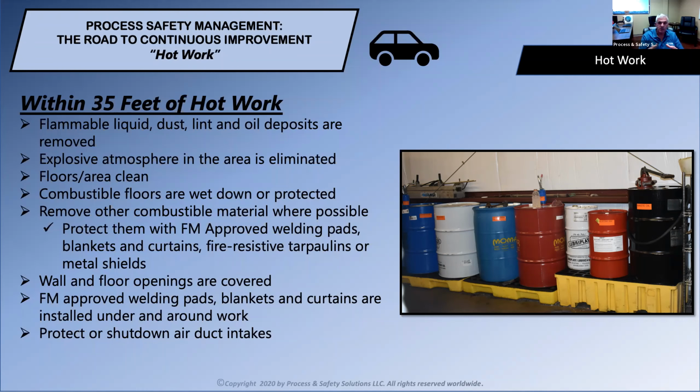A lot of times within facilities that we go into, they will have multiple areas of work. For example, they could be doing the hot work in elevated areas three to four floors up, and have sparks that can fall all the way down to the bottom floor. So you may have to have a fire watch at each one of those levels to make sure you're addressing any fire or potential fire issues.